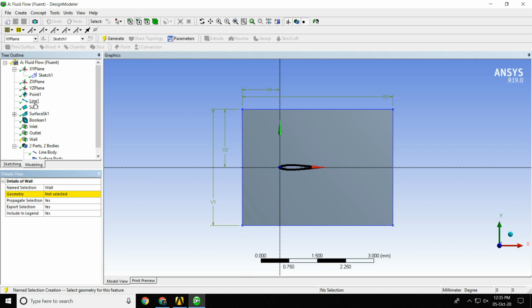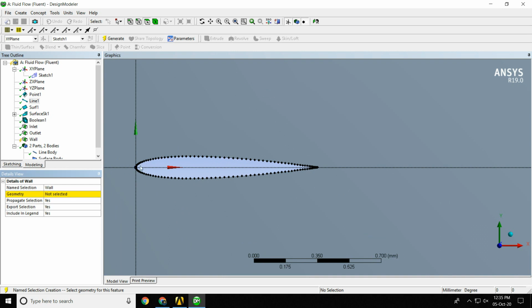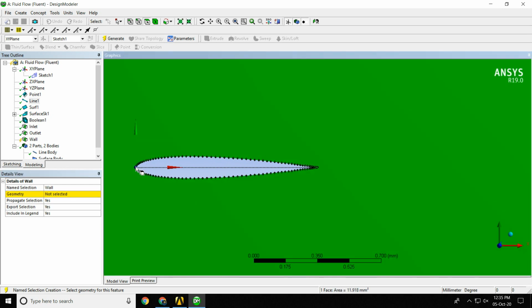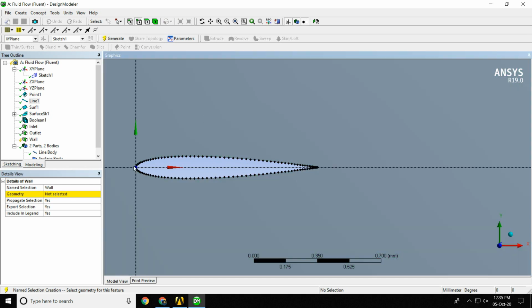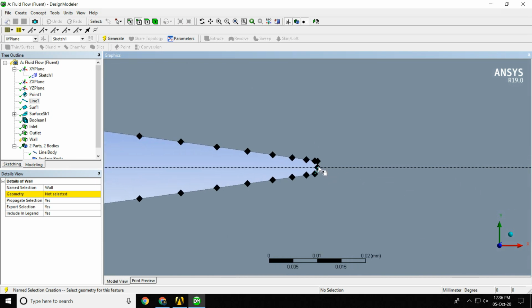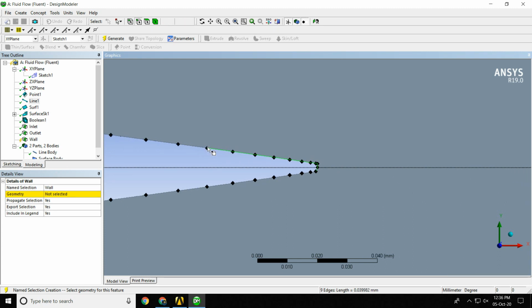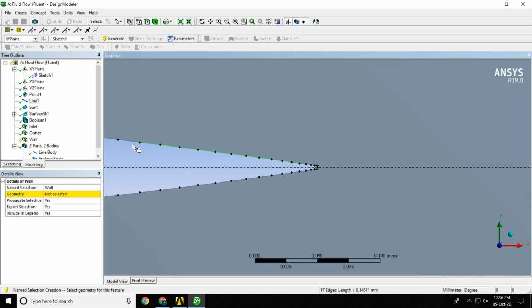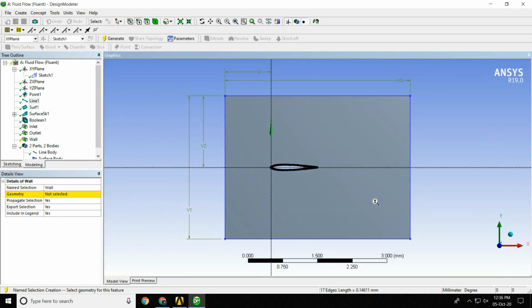Okay. Normally, let me see if I can just check for the wall here and apply. Not able to apply. So you'll have to select it. Click on edge selection. Same procedure, hold control and try to. Or else, wait, let me see if I could use control A option.